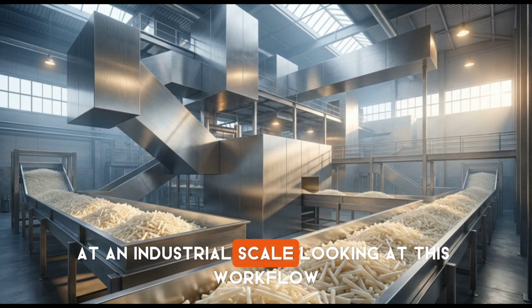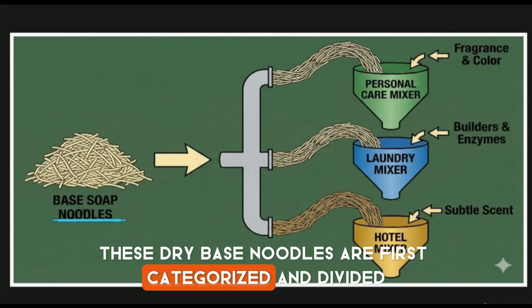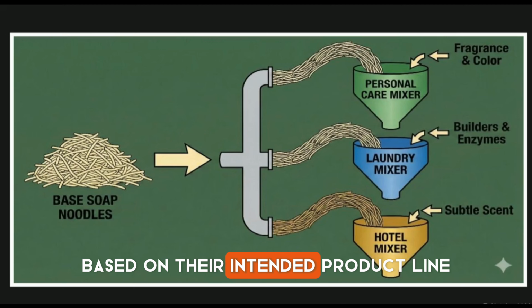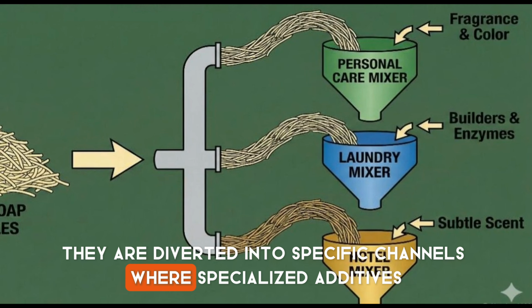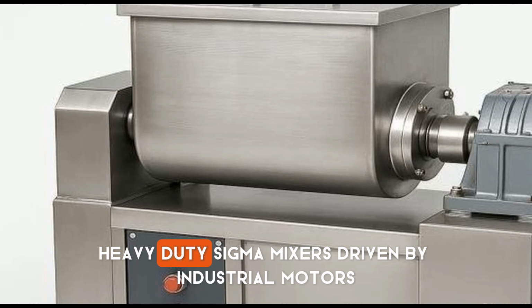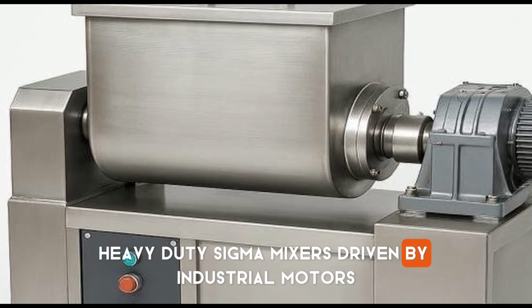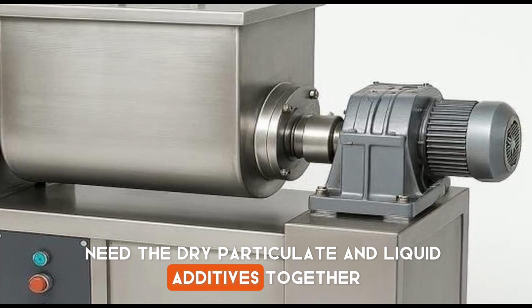an industrial scale. Looking at this workflow, these dry base noodles are first categorized and divided based on their intended product line. They are diverted into specific channels where specialized additives, pigments, and fragrance oils are injected into the mix. Heavy-duty Sigma mixers, driven by industrial motors, knead the dry particulate and liquid additives together.